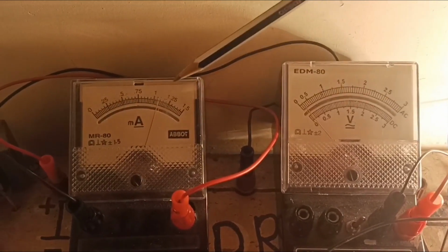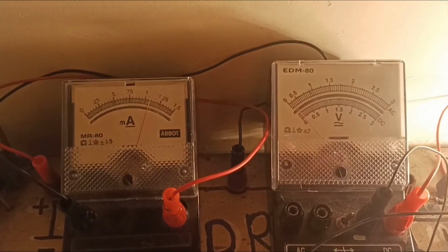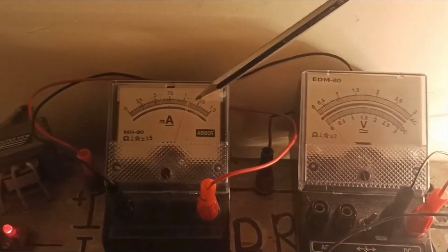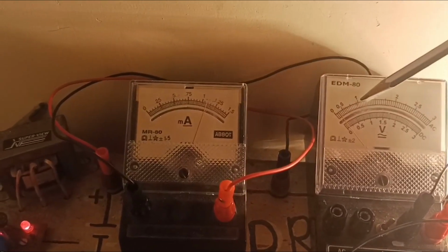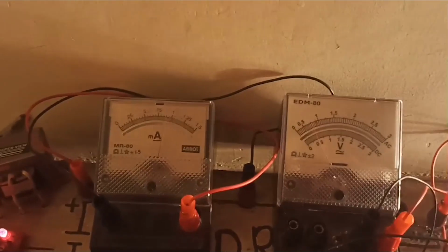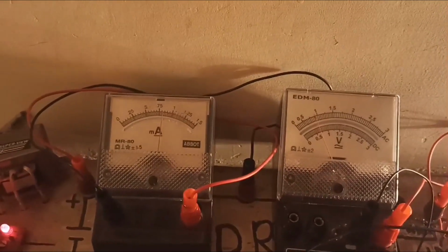Okay, and current increases, means whenever the light falls on this, that time the resistance decreases and current increases. So you just see here, again I am increasing the distance of this lamp. Your voltage increases, current decreases, means the intensity of that light is also playing an important role.